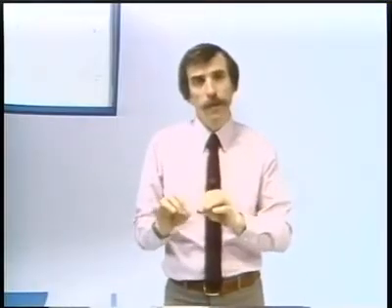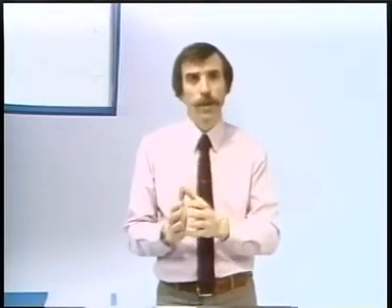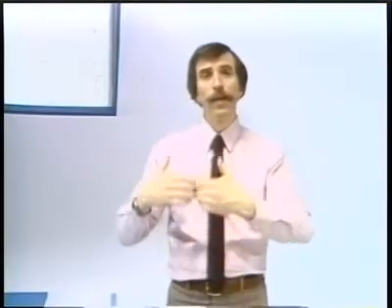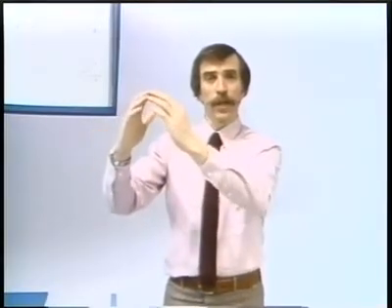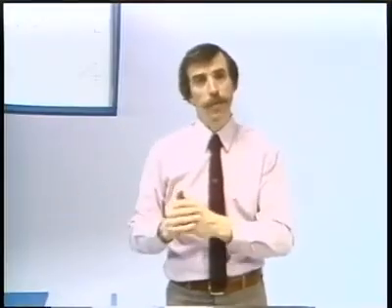In preparation for that, what I would be eager to encourage you to do, using the study guide and in reviewing this lecture, is to begin the next lecture with a careful and thorough understanding of the arguments that I've just gone through, in particular, understanding the process that's involved in going from a continuous time signal through sampling to a discrete time signal, and what that means in the frequency domain in terms of taking the original spectrum, replicating it because of the sampling process, and then rescaling that so that the periodicity gets rescaled so that it's periodic with a period of 2 pi.